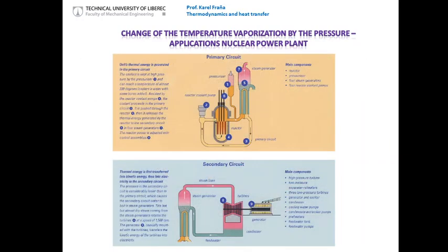On the next slide, it's nothing else than the primary and the secondary circuit. I will be talking about the circuit because it's very interesting from the point of view of thermodynamics. Now we look at the primary circuit. What I told you now, it's a reactor, which is actually nothing else than a heat source. And during the nuclear reaction inside, we actually warm up the water inside. And the pressurizer and the pumps are used to increase the pressure, so keep this water at the higher temperature in the liquid form. That's all.